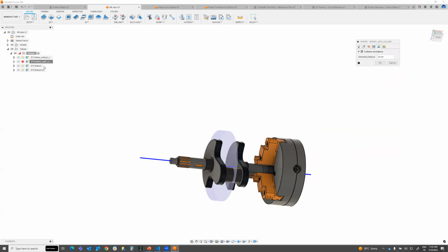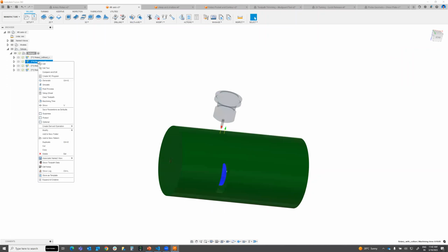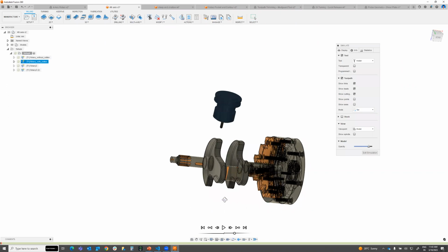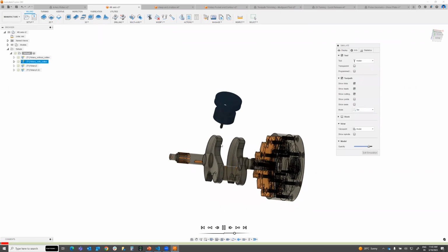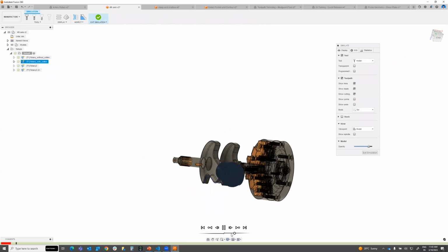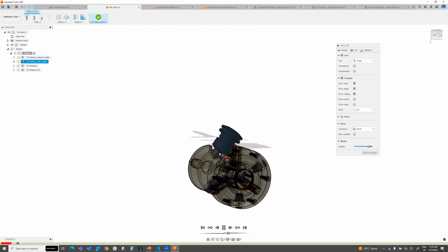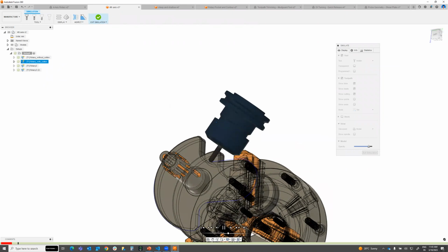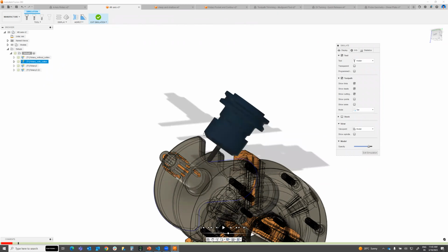Okay, once I go here, you can see the simulation of this particular toolpath. Right click and simulate toolpath. Now we can understand that whenever this tool is coming, it will automatically tilt the tool near that particular point. You can observe here when the tool is coming, now my holder was tilted. Before this, the tool was not tilted. Now we can see the tool is tilted parallel to this surface.